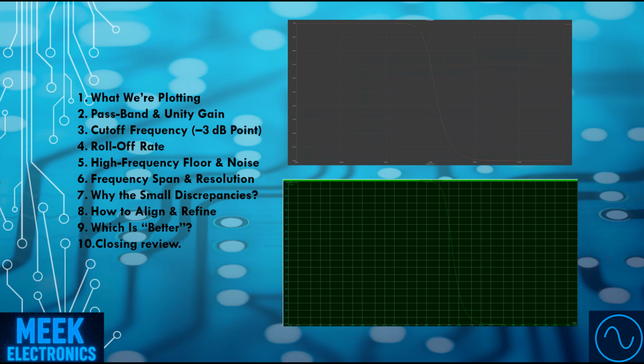3. Cutoff frequency, the -3 dB point. Next, we spot the -3 dB knee. Proteus's falls at about 1.1 MHz, Altium around 1.3 MHz. The theoretical fc for R equals 150 ohms and C equals 1 nanofarad is 1 over 2 pi RC, approximately 1.06 MHz. So Proteus is within approximately 5% and Altium 20% of theory under their default settings.